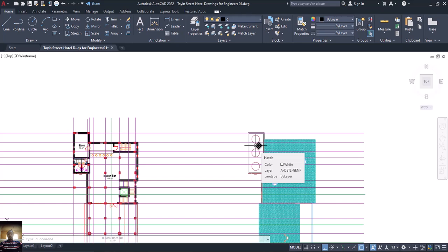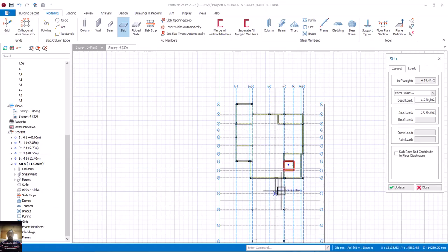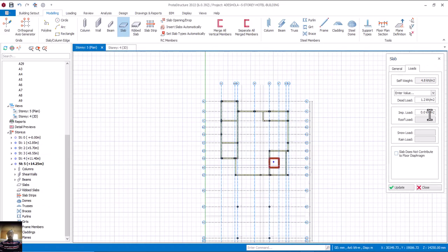First of all, square the 0.91, which gives us 0.8281. Therefore, let's multiply pi, which is 3.142, by 0.8281. If you have done that, you discover that what you have is approximately 2.6019 meter square. Now that we have our diameter converted into meter square, we want to convert to kilonewton per meter square, because this is a surface load at the contact.